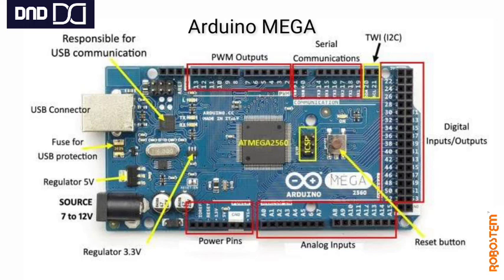And if you see, the difference is only its microcontroller. There it was Atmega 328P. Here it is Atmega 2560. Okay. And the difference we are having here is more digital pins. If you see, in the Uno we are having only 0 to 13, but here we are having 0 to 53.